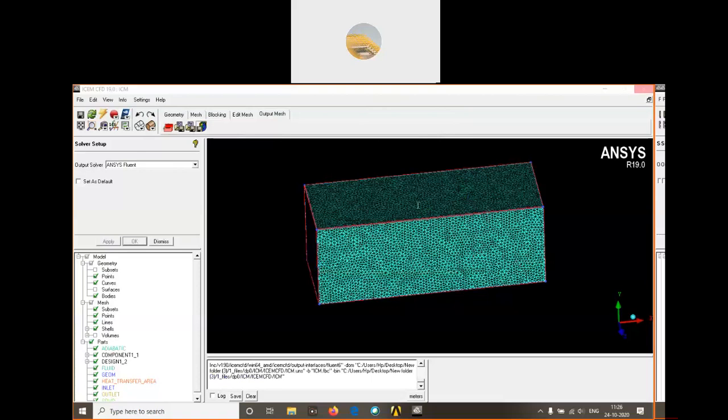There is some question. I'll tell you. Is there any option to use combination of polygon? Yeah, definitely, Shakib. The thing is a bit advanced, okay? Because students are from second and third year, so I have not gone into polygonal meshing. But we have something called polyhedral meshing, which is in ANSYS Fluent, which is in Star-CCM. The main objective of polygon is to reduce the mesh count. If you use tet mesh, if you use hex mesh, the count will be like 10 lakhs, 20 lakhs, even in some case 1 crore, 2 crore.